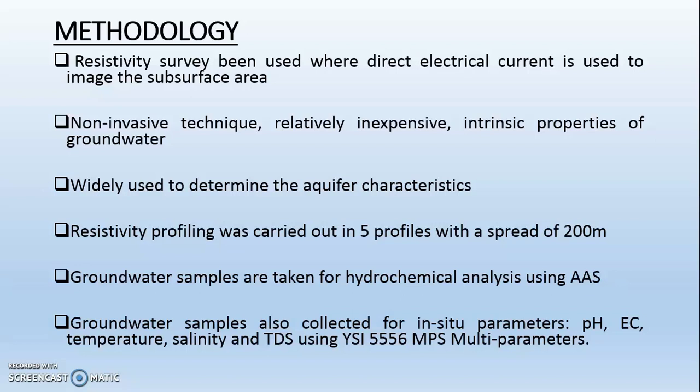For in situ parameters, we test for pH, electrical conductivity (EC), temperature, salinity, and TDS using YSI 556 MPS multi-probe parameter. I would like to show some of the pictures during our resistivity survey.